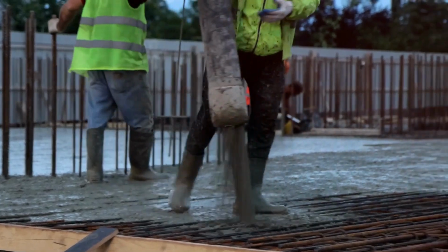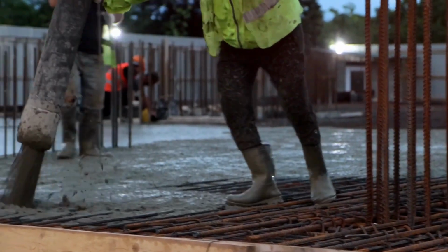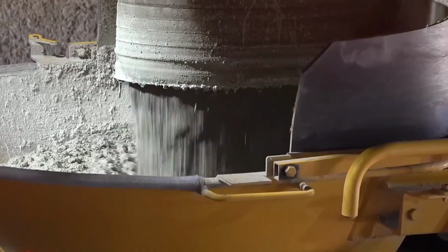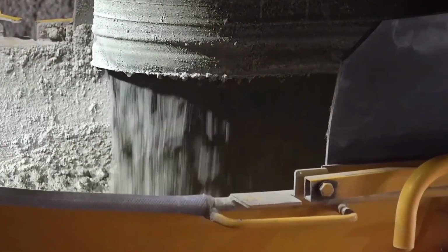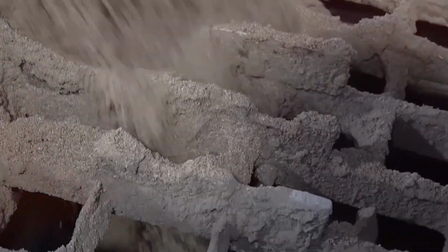After the mixing process, the concrete is transported and placed at the final location. Whether poured directly into formwork molds or using specialized equipment such as pumps or conveyors, it is essential to avoid segregation. Compaction, using vibrating equipment or mechanical means, follows to eliminate voids or air pockets and ensure the strength of the concrete. Curing is the next critical step, maintaining sufficient moisture and temperature conditions to allow the cement to hydrate and gain strength.